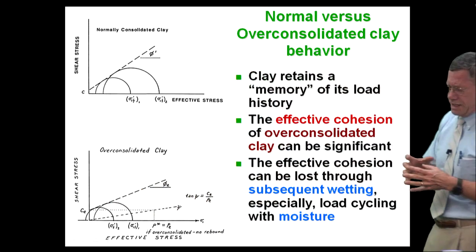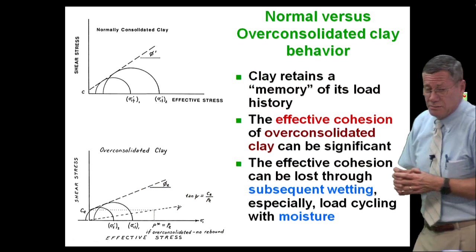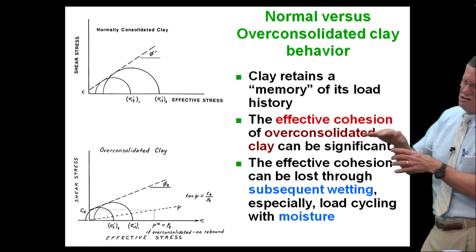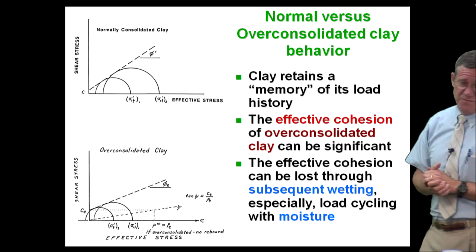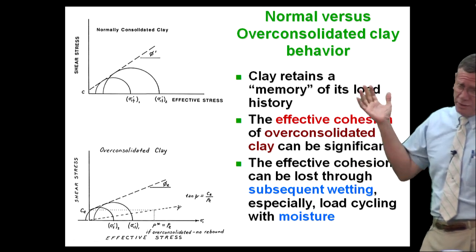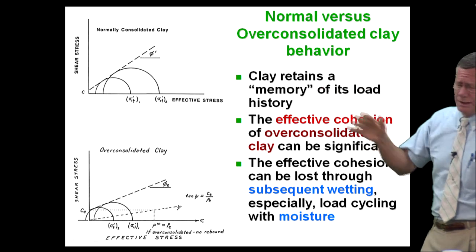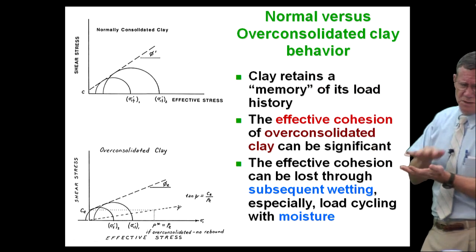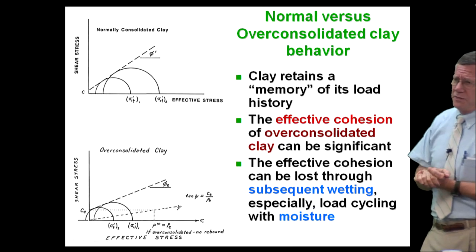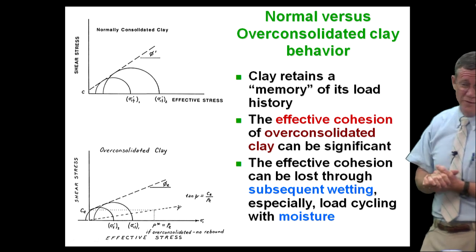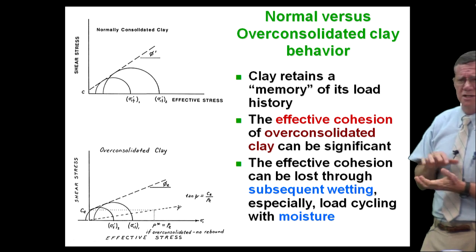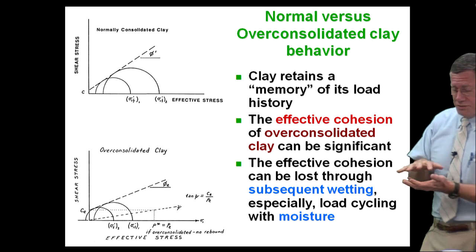drained conditions. So if we take a direct shear test, ASTM D3080, standard cheap direct shear test, you can shear the specimen at 0.05 inches per minute. That is fast in the world of clay. We're talking permeabilities of 10 to the minus 6 and lower. That's really fast. If you took that same specimen and instead of shearing it over a period of 30 minutes, you did it over a period of 30 days, which is like it is in the real world, in the field, you're going to get a whole different answer. Because you're getting pseudo drainage while you're shearing.